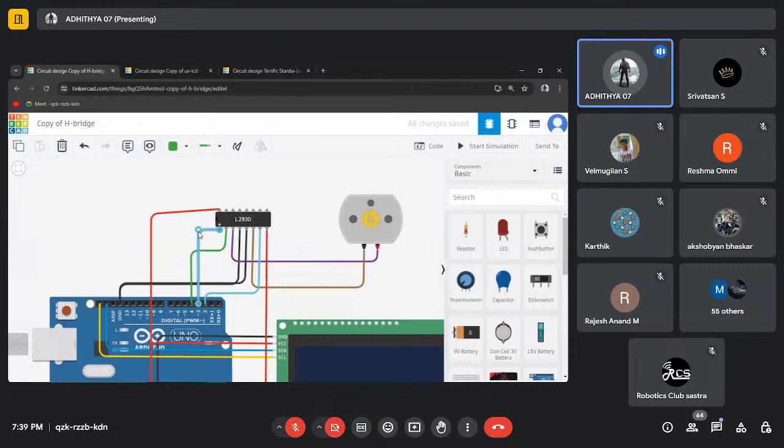Here, as I said, we need to be scaling it from 0 to 12, so in the code we can use values from 0 to 255. Think of PWM like a water bottle you are filling with water, but the bottle also has a hole which is consistently leaking out water. To maintain one level of water, you need to control the flow of water. Once you increase the amount of water falling into it, it changes the level at which it stays. That's the basic concept of PWM.